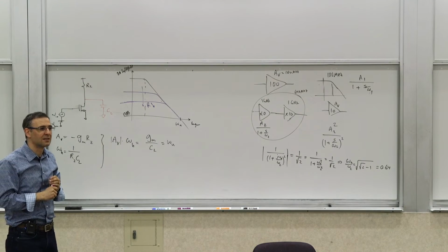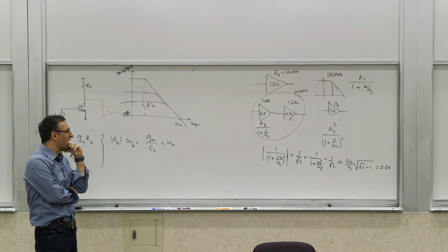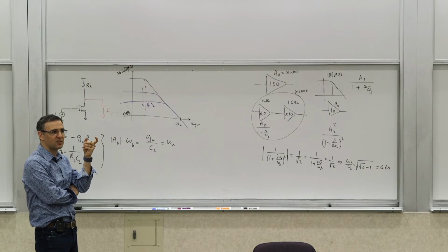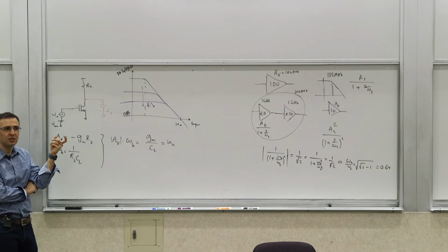Yes? It's not just, I mean, open loop at lower frequencies, right? Because if you're open loop at a higher frequency with parasitics, you can still get an unintentional feedback from some parasitic. Right. This assumes that these amplifiers are not strongly coupled to each other. And there are scenarios, that's a good question.